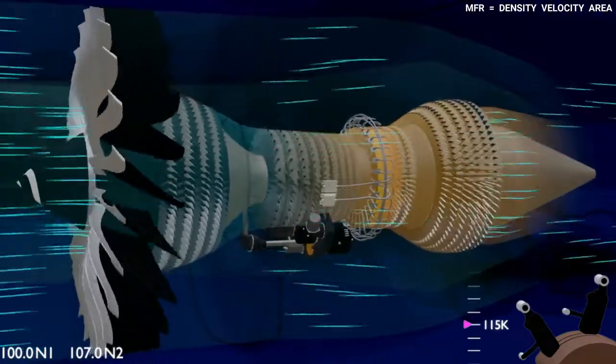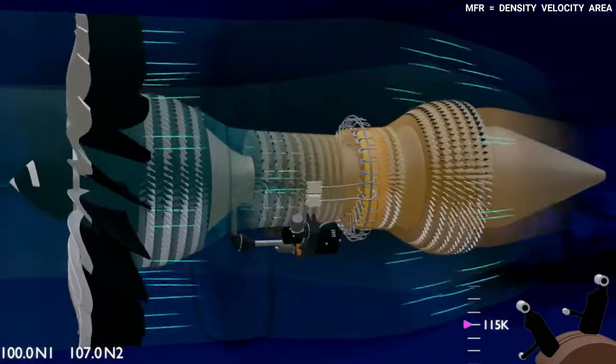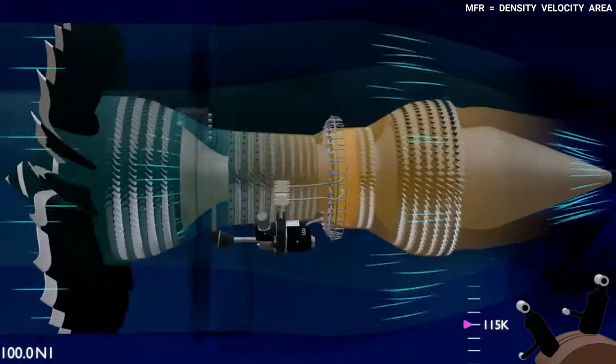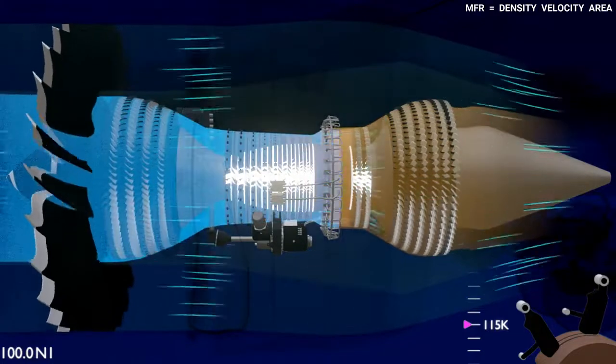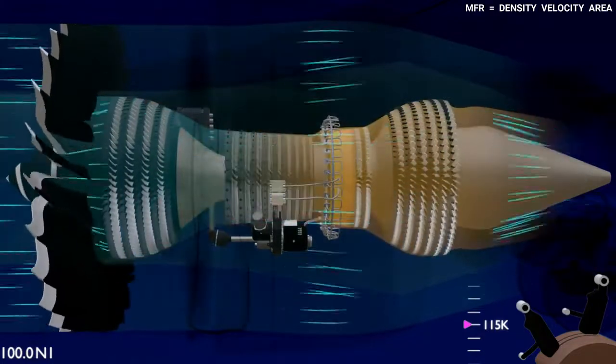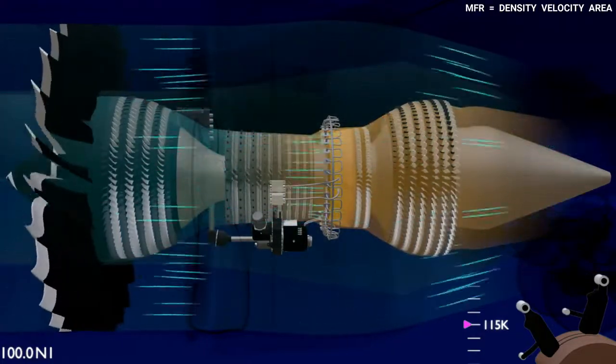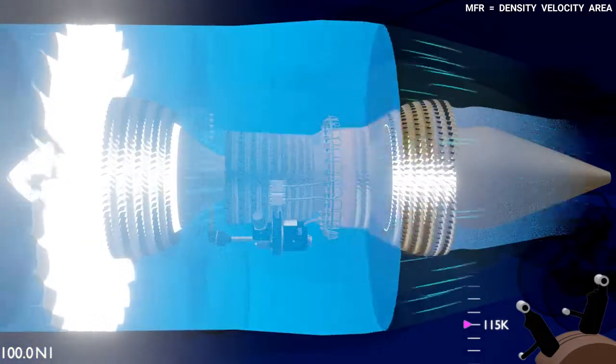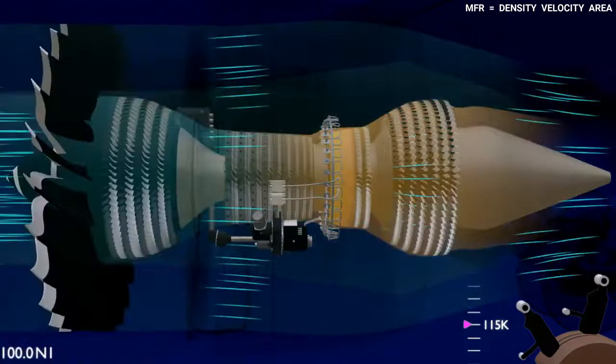The EEC controls the thrust produced by the engine by controlling the N1 shaft speed, and does not use the N2 shaft to control the engine thrust, as the N2 shaft only deals with the core airflow, which contributes a small part of the engine thrust. Whereas controlling the N1 shaft gives control over both the core and the bypass airflow, that is, the full engine thrust.